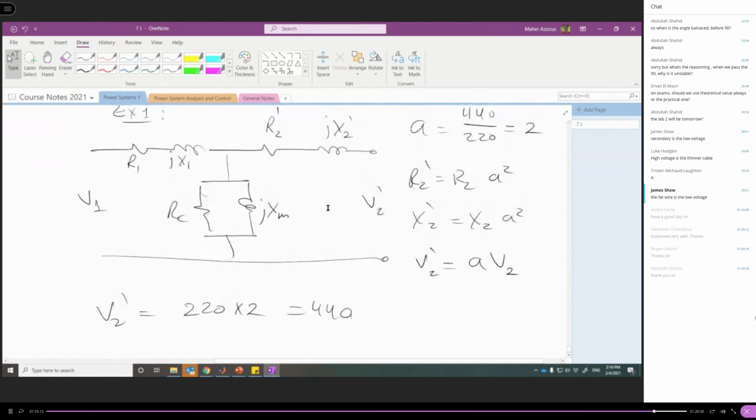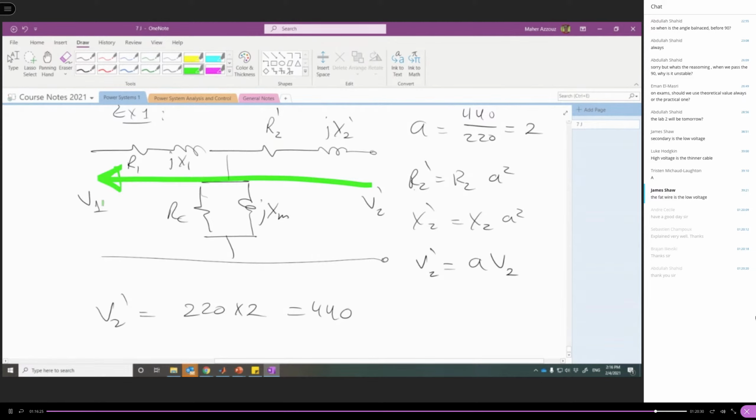The idea here, as I told you, since we need to control the voltage across the load, is to start backward. We start from the load and move from the load to the source. Why? Because we want the voltage across the load to be regulated. So the voltage here is known, and the power consumed by the load is known. So we know everything on the load side.